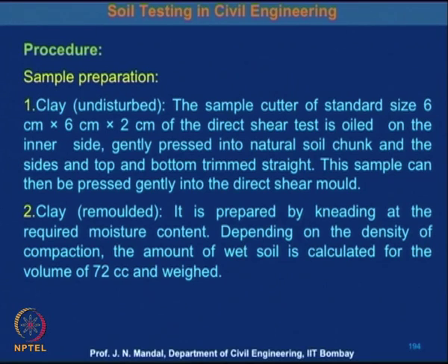The sample cutter of standard size of 6 centimeter by 6 centimeter by 2 centimeter for direct shear test is oiled on the inner side and gently pressed into the natural soil chunk, and the sides, top and bottom are trimmed straight, and this sample can then be pushed into the direct shear mold.